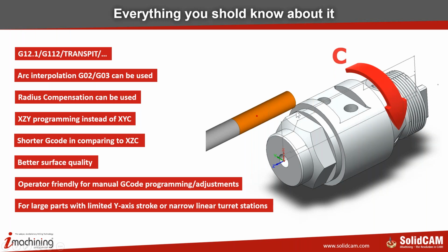As you can see here, even if it's a very straight line on this hexagon, for each interpolated point you need to add a new point in order to get a good surface quality. And depending on the interpolation, the better the surface quality would be. Doing this completely manually is not an option for manual programming. So that would be catastrophic.